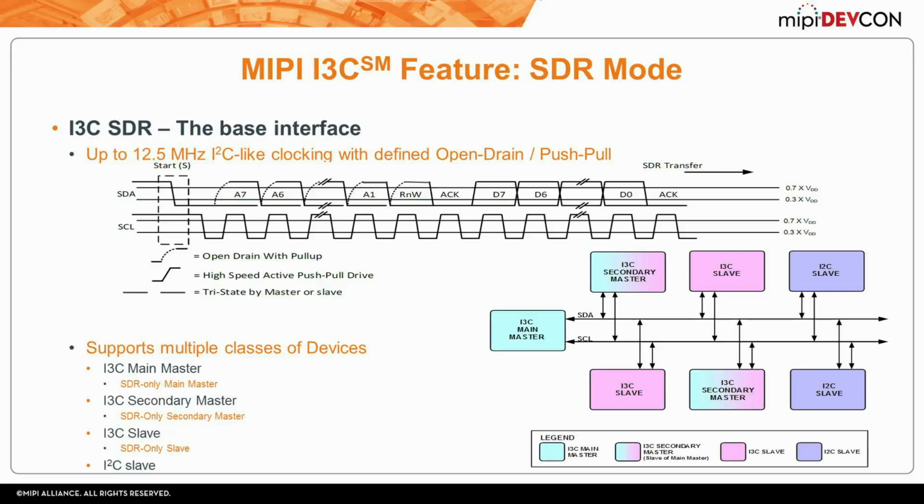on the bus. So I3C SDR functions very much like that, except there are instances, for instance, for a start condition, the bus needs to be available. It needs to return to open drain on both of these lines, such that the master or an interrupting slave can drive this low. And then the first byte on the bus, the address here needs to be arbitrated, right? So there needs to be winners and losers, and you do that by allowing open drain through that segment.